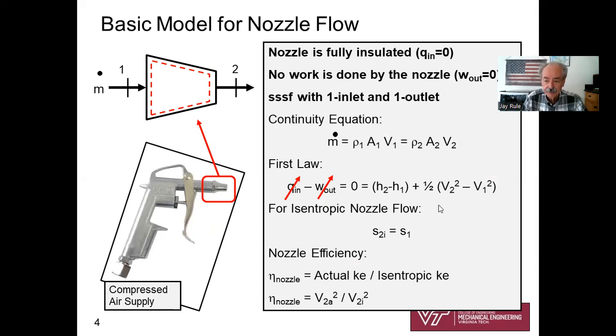And so in general, the way to think about nozzle flows, given a fully insulated nozzle, do you see that there's an interchange between enthalpy change and kinetic energy change? The sum of those two has to add up to 0. Enthalpy change, kinetic energy change.